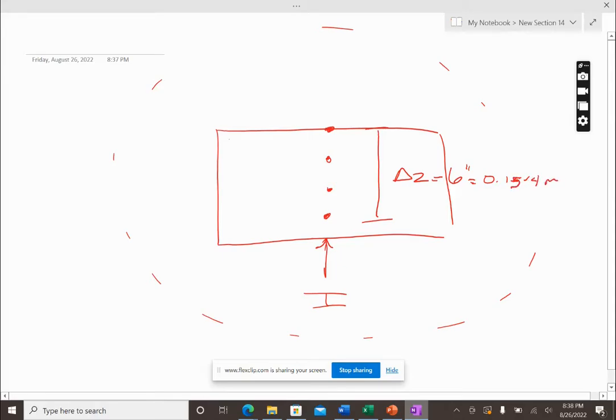Okay, so to measure the ambient temperature, we knew that heat rises, and so there's going to be some influence at a region above the slab. The ambient temperature is going to be hotter above the slab. So we took the temperature away from the slab, using a thermocouple, and measured the approximate ambient temperature.